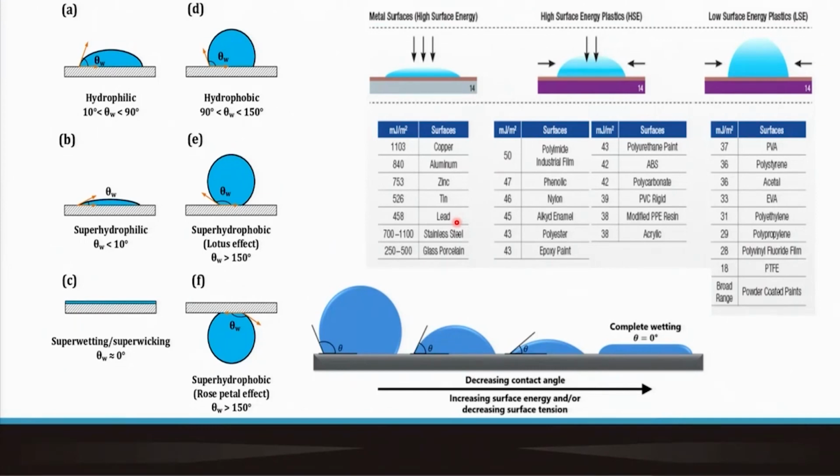So in case of metal, we have a free electron cloud. In case of polymers, we allow the neighbors to share the electrons between the nearest neighbors. So that's covalent bonding. And in case of ceramics, we see a predominant nature of electrons getting transferred from the cation to anion, and that's how they form a non-directional bonding of very high value.